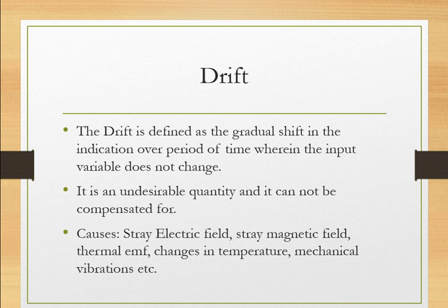For example, consider changes in temperature. Any instrument contains different types of resistive elements and semiconductor elements inside it. A semiconductor element is very sensitive to temperature. If you increase the temperature surrounding a semiconductor material, there may be a bad effect on its resistance, and in turn we get a change in the current. That may be harmful or undesirable. That's why temperature has an effect in most instruments.